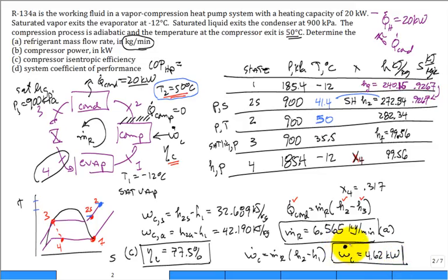So if you ran that for 1 hour, how many units of electricity would you have had to pay for? You'd have to pay 4.62 kilowatt hours. What's the value of that? What do you pay for a kilowatt hour of electricity in San Antonio? Roughly about 10 cents. So if you ran that system for an hour, it would cost you 50 cents.